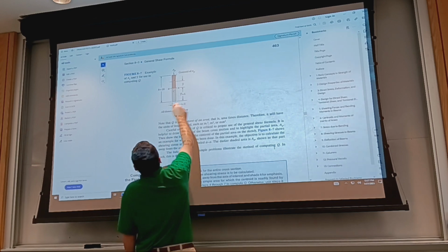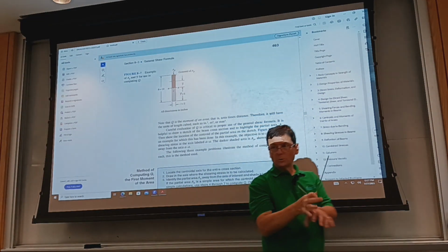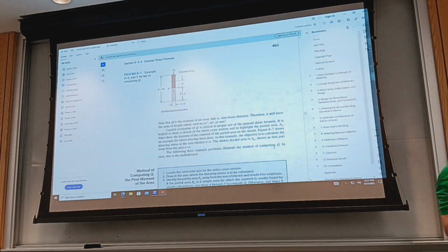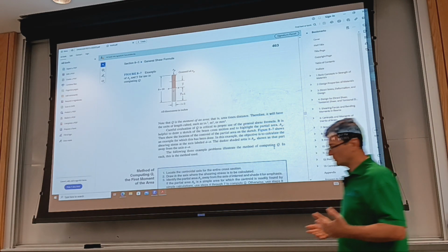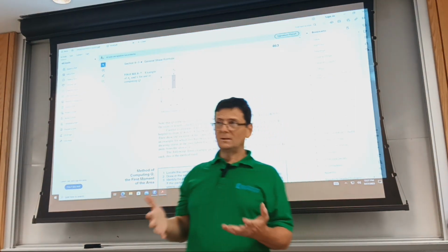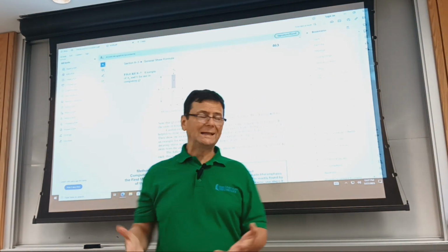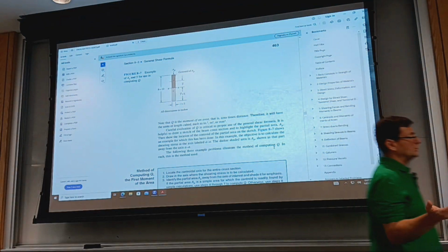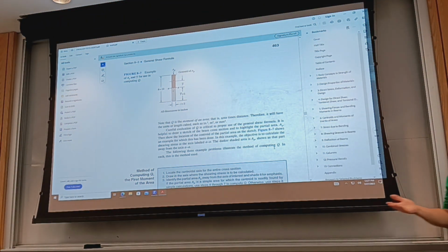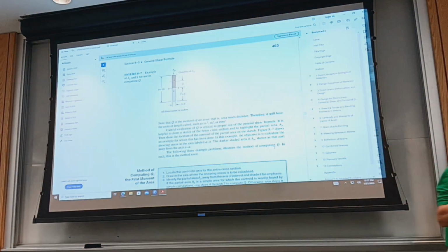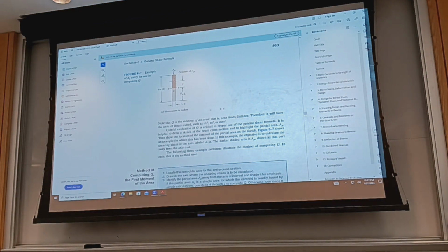Of course, I can analyze it elsewhere than through the centroid. It could be at a plane of interest where that joining happens. I said you can use fasteners, or it could be glue. The book discusses the case of nail fasteners, for which we know the amount of shear force capable per fastener. We can also analyze it if you use glue, or if you use discontinuous weldments.